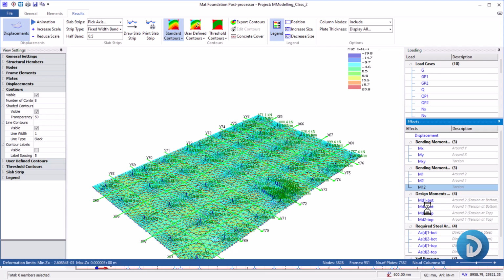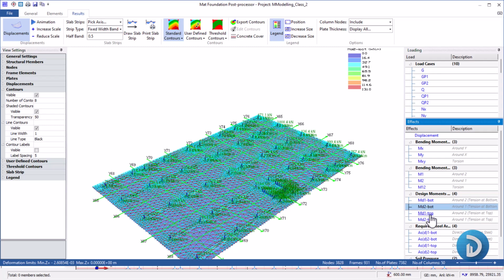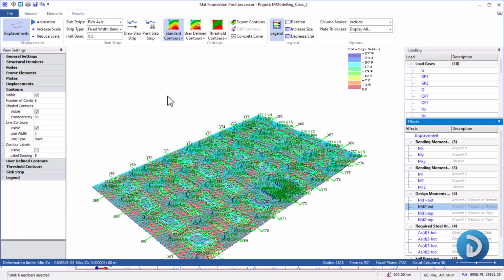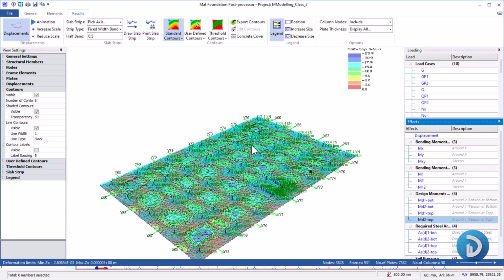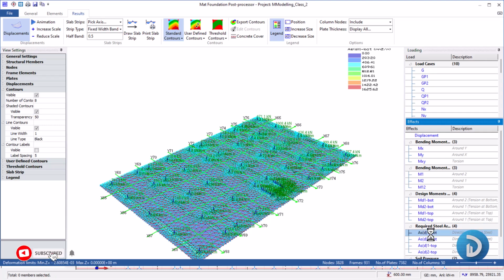And do not forget the issue we intend to solve with respect to the cantilever we've created. So we'll click here and click on the last one. Okay, so our challenge was our required area of steel. So now if we come down here to click our area of steel required, you can see the maximum value for this area has been reduced.